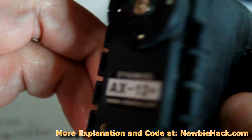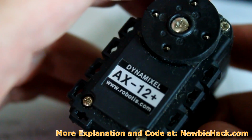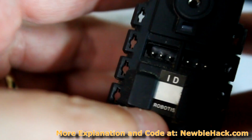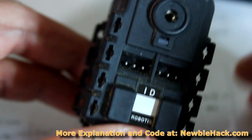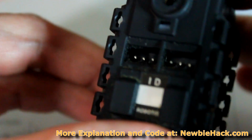One is for ground, one is for power, and the other one is for the communication. And this is a digital servo, so it actually uses a UART communication form to be able to turn the horn here. It has an ID. Let me see where the ID is. Yeah, I haven't assigned this ID yet, but I can assign this an ID, and I can tell this particular servo over a line of a whole bunch of servos, this is the one that I need to talk to, and this is the one that needs to perform the task that I give it from the microcontroller.